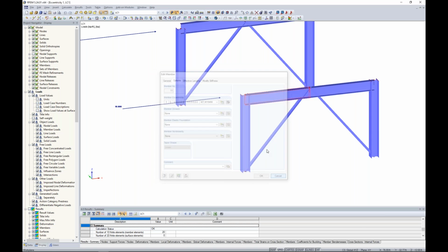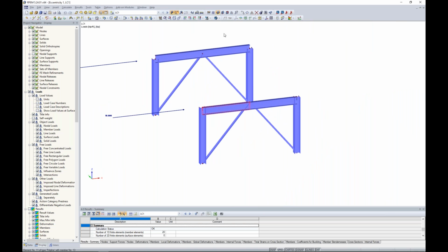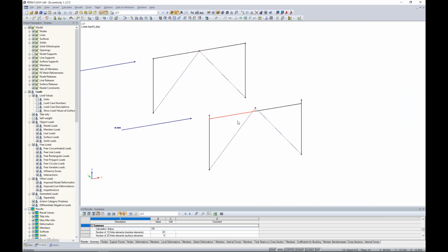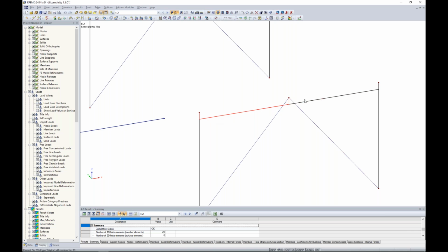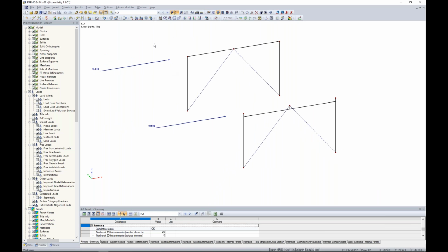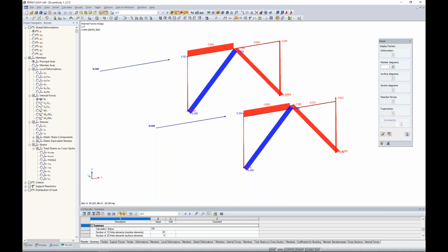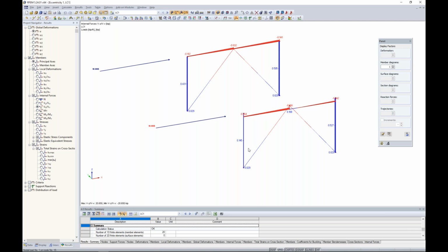But point being, we could have even taken this a step further to move the eccentricity from the axial offset here as well. When we turn this to wireframe view, we can see this member drop down below here, again with those rigid-type elements being taken into consideration with the stiffness matrix. A lateral load is applied here. So we run this analysis, and when we take a look at our results, pretty much everything looks to be fairly the same. We're taking a look at our axial forces. Maybe we take a look at our shear forces as well.